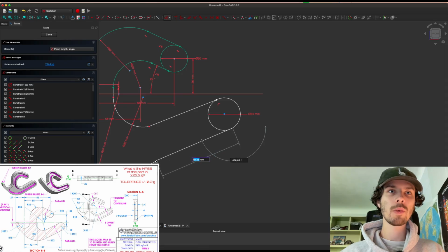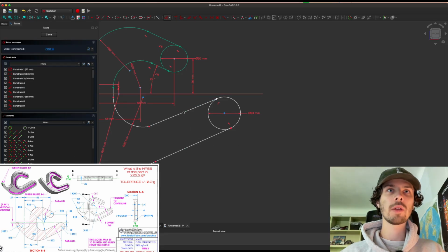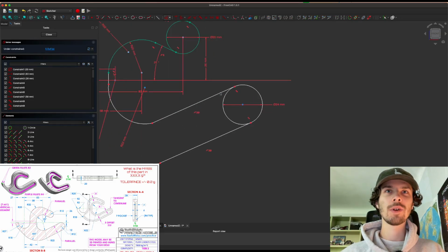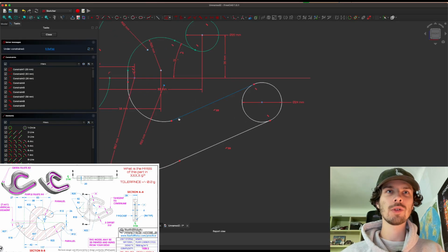Connect them up, make them parallel over this here, or just press P with a shortcut. It's always important to have efficiency. It's not great if you're working a full day on one piece. So as one line is there, as they're parallel, one tangency makes them both tangent to the line. Here as well, tangency everywhere.